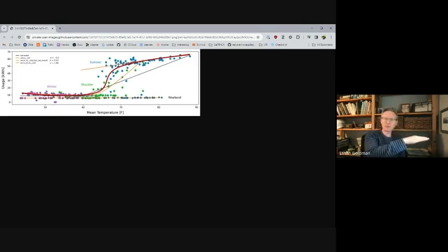You're going to go back to just base load because the heating load is going to entirely switch to a secondary system that's fossil fuel, and so you'll have a straight up discontinuity in the linear regression. Only something that's doing more like a bin analysis and isn't assuming that there's a contiguous line, like all of our models have always assumed, is going to be able to follow that with any satisfaction.